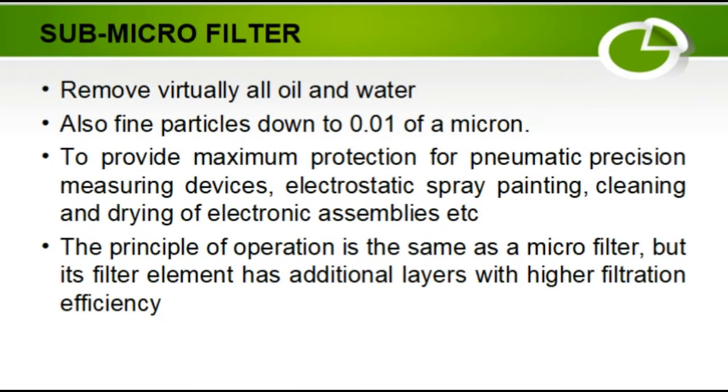Submicrofilters remove virtually all oil and water, and also fine particles down to 0.01 micron, to provide maximum protection for pneumatic preservation, measuring devices, electrostatic spray painting, cleaning and drying of electronic assemblies, and others. The principle of operation is the same as a microfilter, but each filter element has additional layers with higher filtration efficiency.